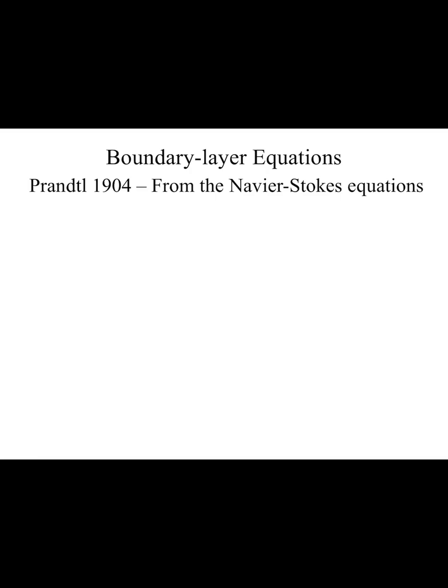And it grows as we move downstream, or as the Reynolds number increases. We're going to continue talking about the boundary layer today, and the first thing that we're going to talk about is actually the boundary layer equations. These were derived by Prandtl back in 1904, and they start from the basic Navier-Stokes equations.